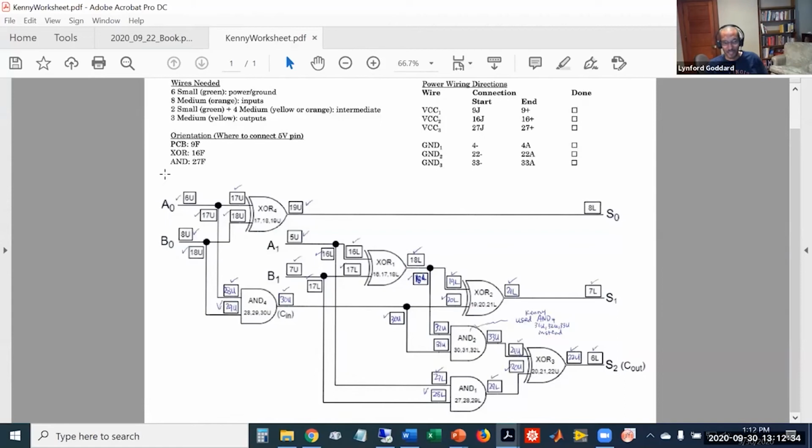So what we ideally should do when working with the students is have them go step by step. So they test this very first XOR gate by itself. That was project 14.1. And then the second thing would be to test the half adder. I believe this was 14.5, before building the full circuit. So piece by piece checking of the project as you're building is a very important takeaway from this activity.